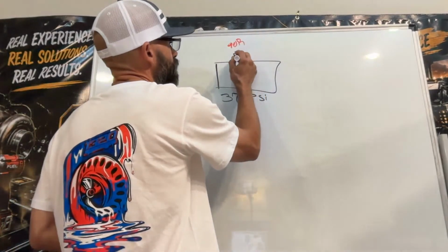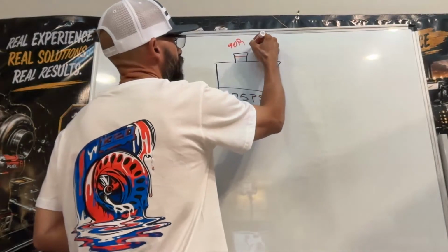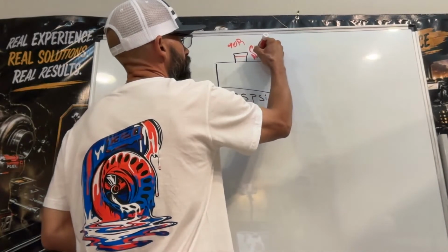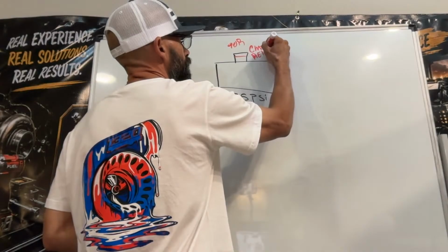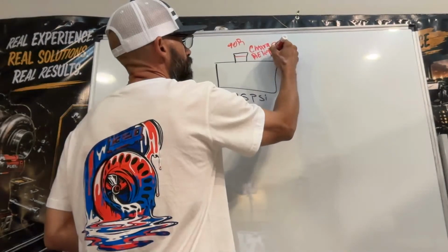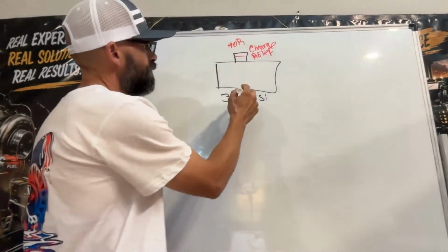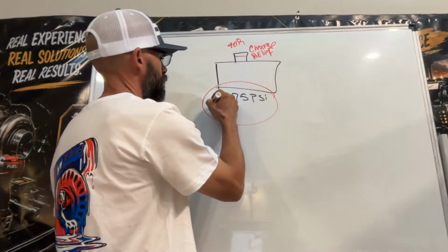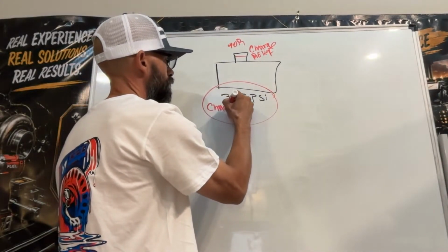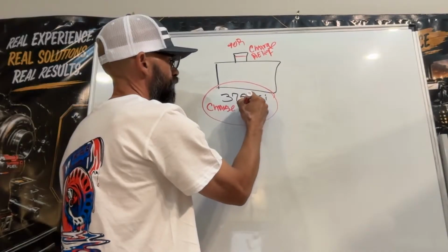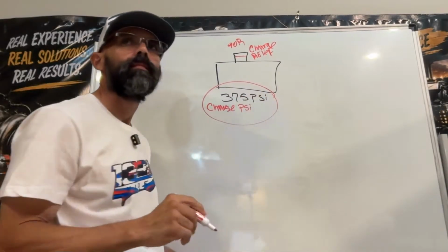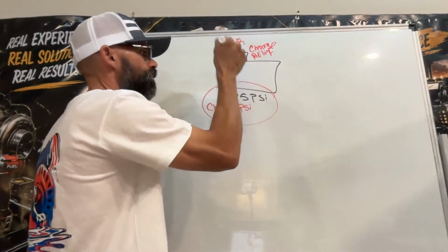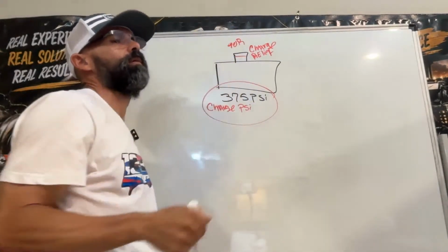So this is your charge relief, right? So this pump right here calls out for 375 psi of charge pressure, right? The manufacturer's data says this pump needs to have 375 psi as charge pressure.